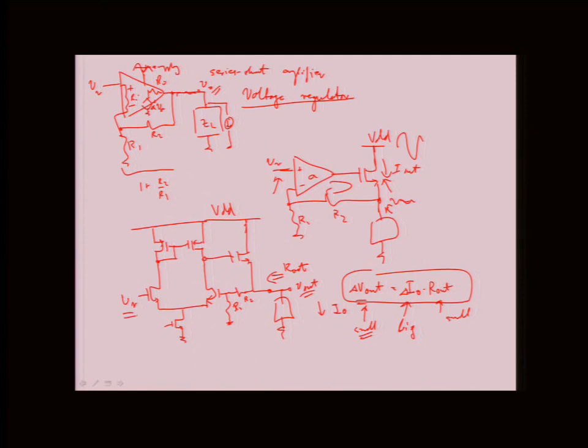Usually it's some reference that you build, and we've done references in the middle of the term, and you know that these references have some circuit that is attached also to the supply voltage and also has some power supply rejection, that any small signal change in the supply will percolate out to a change in the reference.